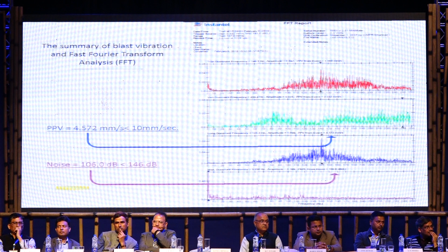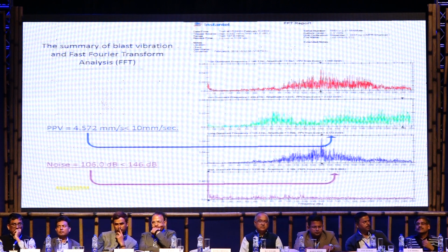Our requirement is to keep the peak particle velocity of the existing structure, meaning the existing tunnel, within 10 millimeter per second. That's how we designed our control blasting methodology here, and we kept it within the 10 millimeter per second.